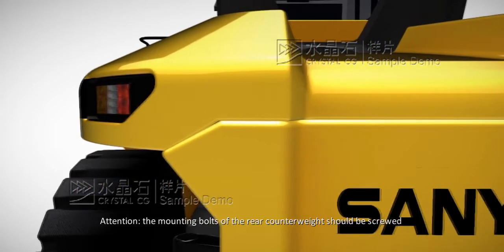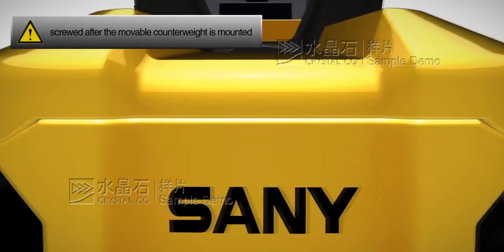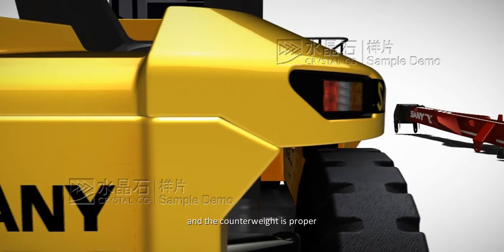Attention! The mounting bolts of the rear counterweight should be screwed after the movable counterweight is mounted. After fine tuning of the rear counterweight position, screw them with the required torque when the clearance between bolts and the counterweight is proper.